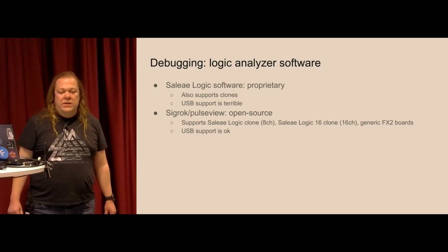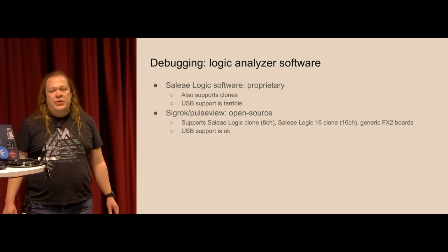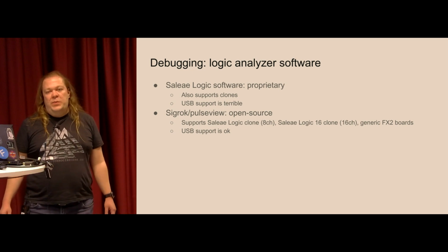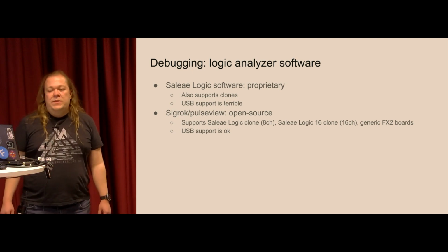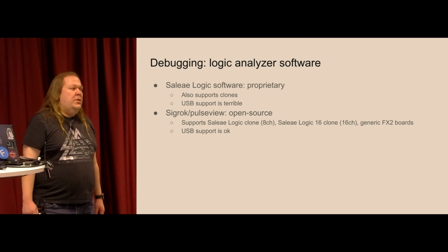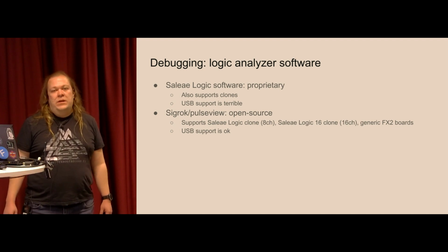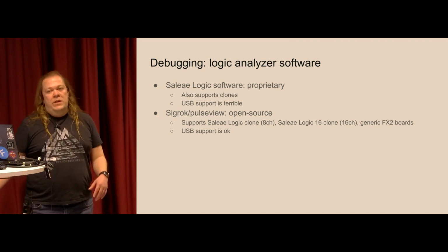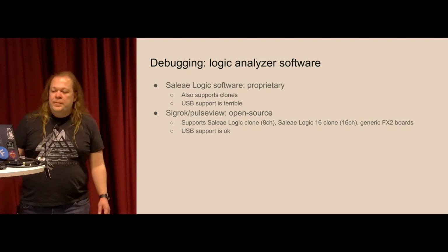And yeah, there is also an option if you want to use proprietary software for capturing, then you can export data from proprietary software and use it in the open source software. Not so convenient, but the second option works great for USB, and it shows you all the transactions in different details, so you can choose whether you need very low level representation or the highest level when you have requests.